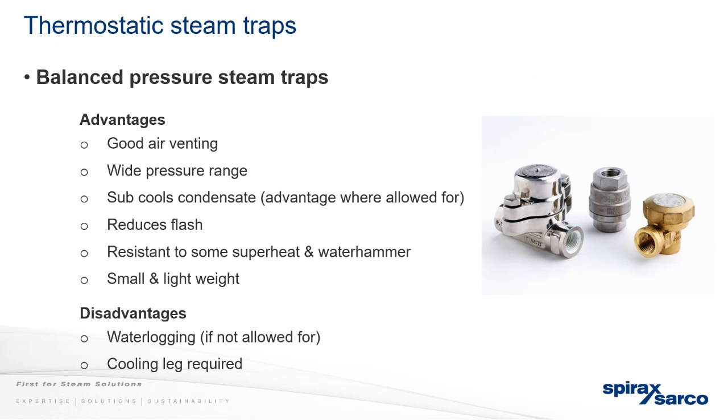Superheat would effectively overexpand the capsule and can damage it eventually. Water hammer again, it's a pressure, and it's a large pressure from water hammer at times, so that can distort anything. And they're small, lightweight, so they're relatively easy to install at heights in small spaces.